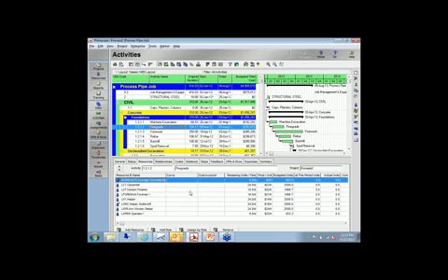Okay, so let's do some changes now. Let's make some changes in Primavera, push those back to Hard Dollar, and then let's go the other direction. Right now you can see this project looks like it's starting around January 2nd. It's about 416 days total. Let's make some changes to both of those things. Let's affect the total duration, and we'll affect the start date, and then go back into Hard Dollar and see how that impacted some of those costs.